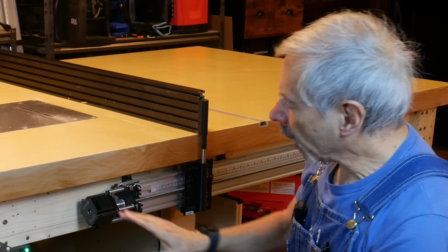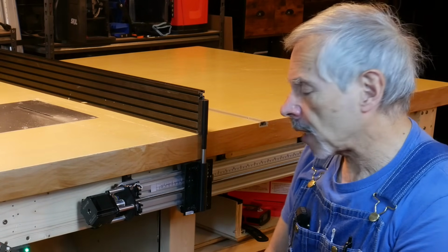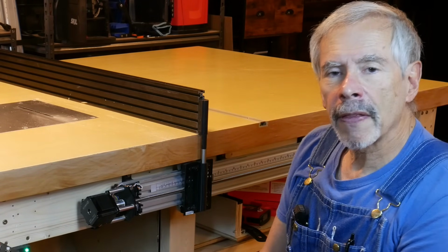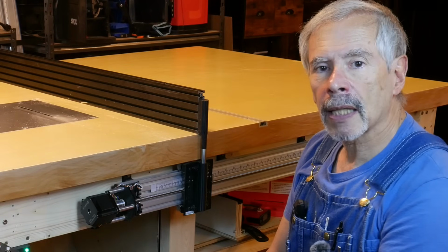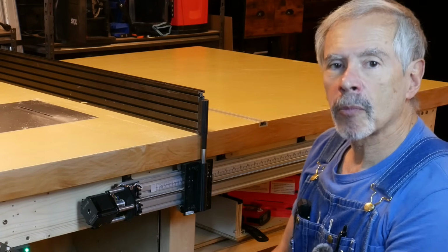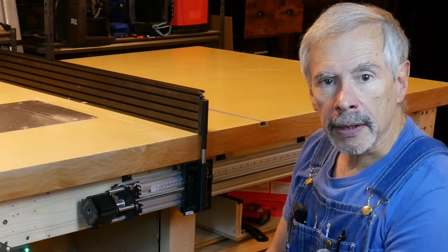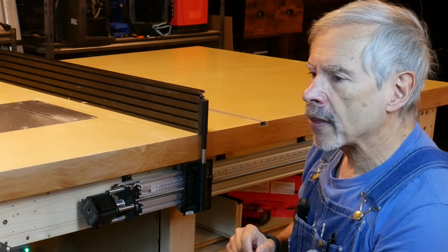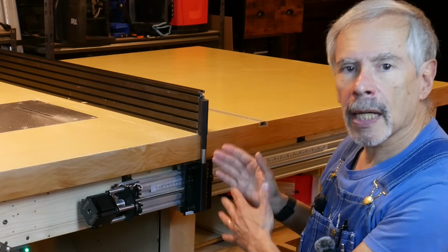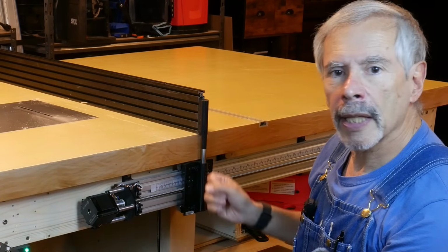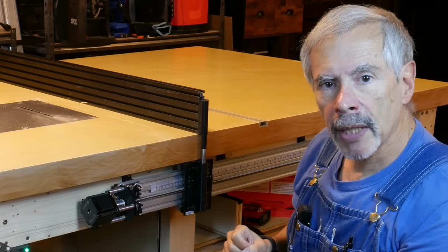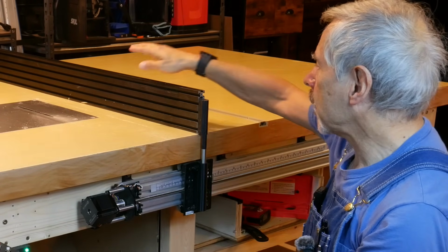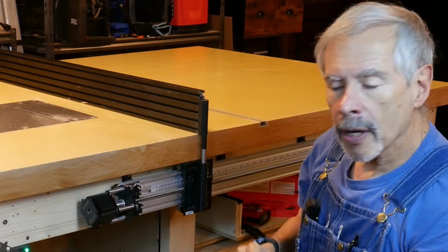The reason why I chose stepper motors for this application is that it is very easy to make stepper motors run at the exact same speed and through the exact same distance, simply by sending both of them the same number of pulses. So if I send this motor 1,000 pulses and the motor in the back 1,000 pulses, then they both advance the exact same amount. And if I coordinate the pulses so that they happen at the same time, then they move in unison, synchronously along, and keep the fence nice and parallel to the saw blade.